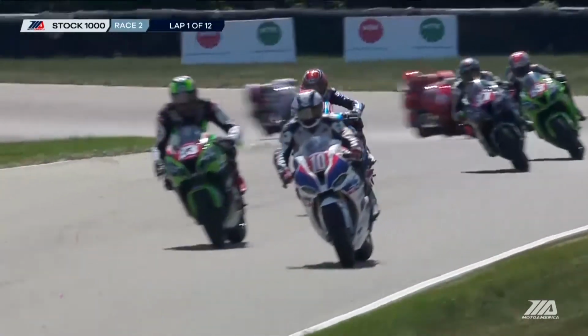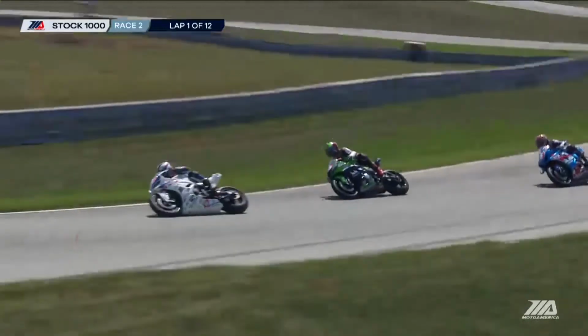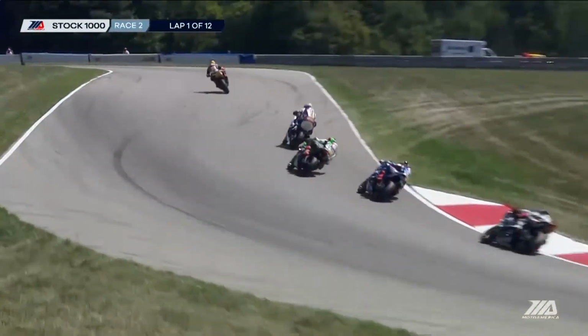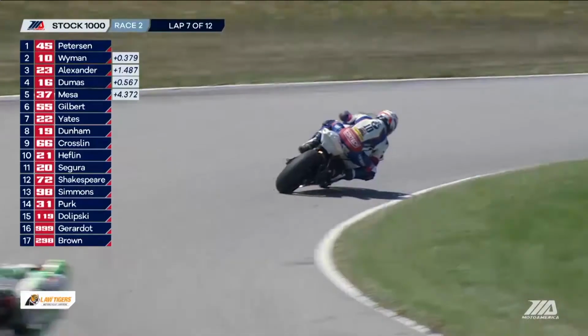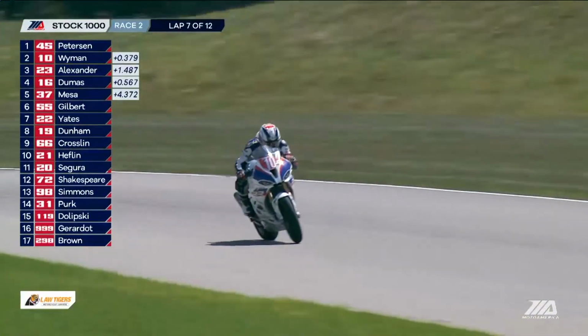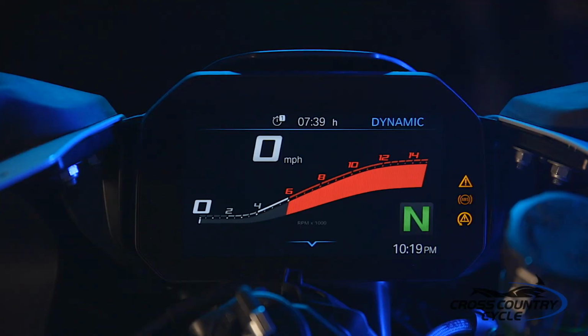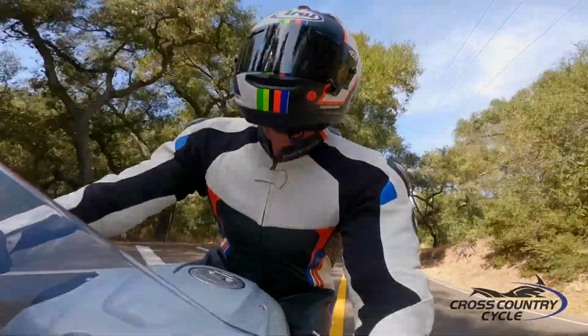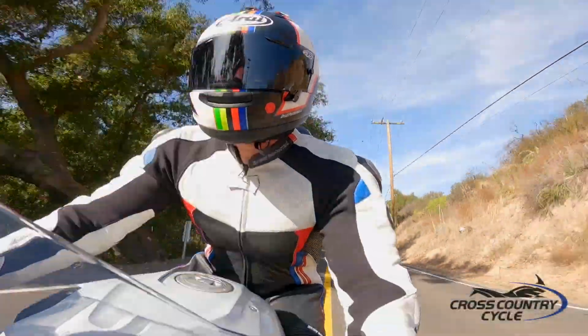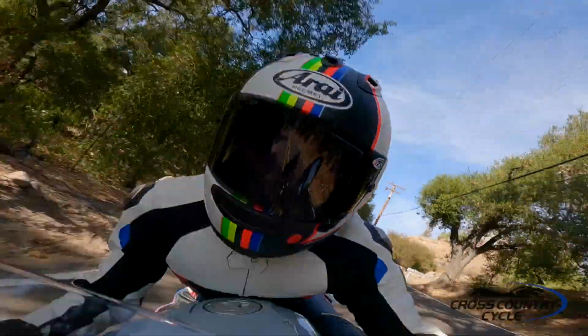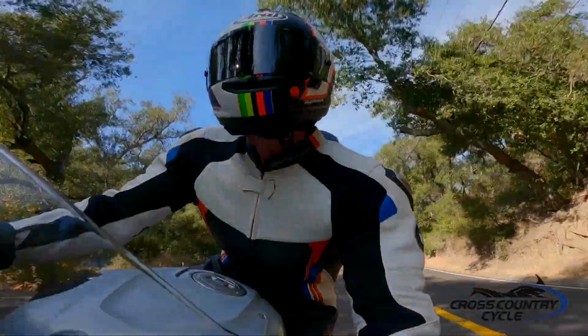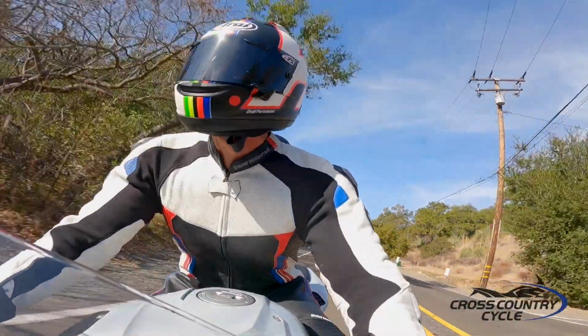It is an excellent option to start with if you haven't been working with damping characteristics in the Race Pro modes. The dynamic damping control is stiffer, providing more damping support for the higher speeds, acceleration, and deceleration you'll have on the track. Dynamic mode is specifically for spirited rides on your favorite twisties in which roadways are smooth and dry. The damping is slightly softer than race mode, as this takes into account that roads are generally rougher than the racetrack.